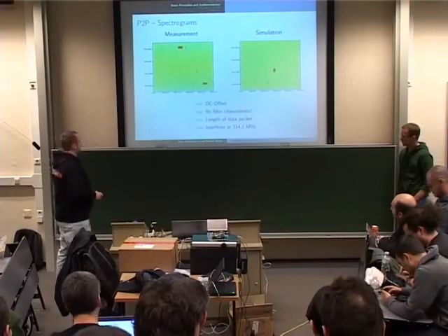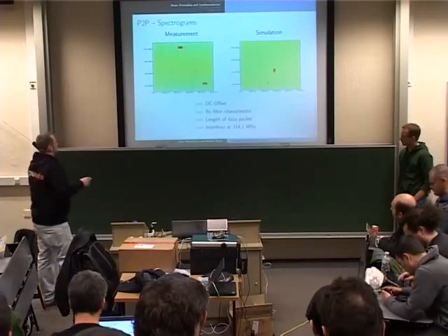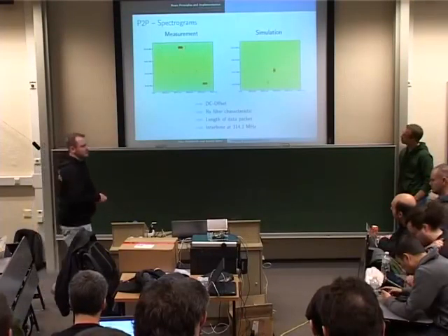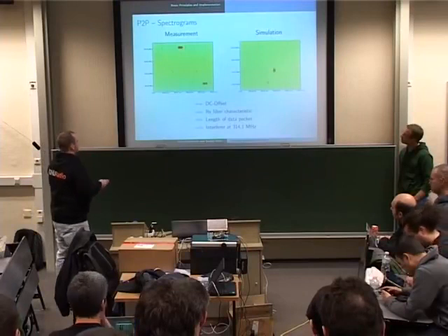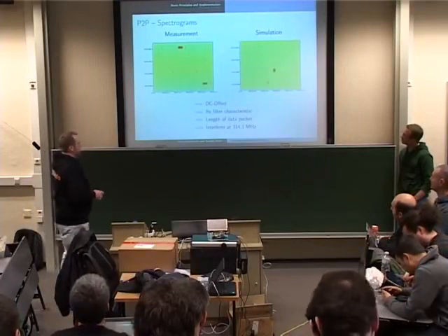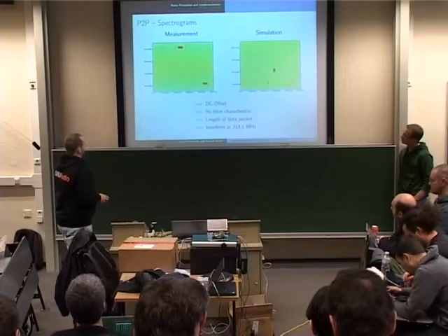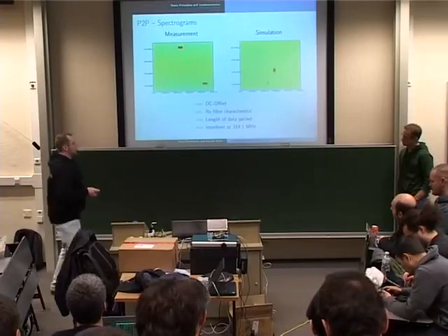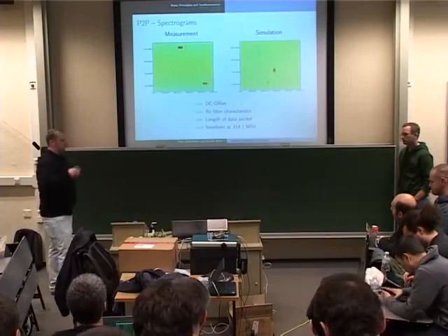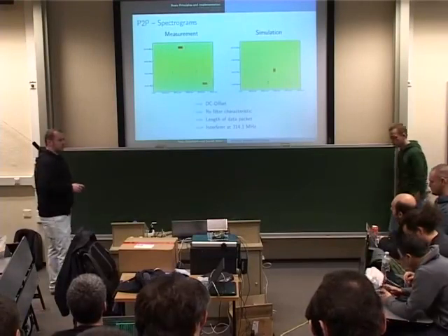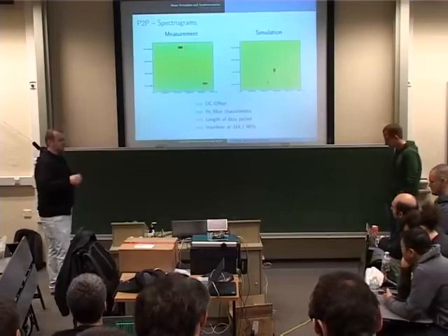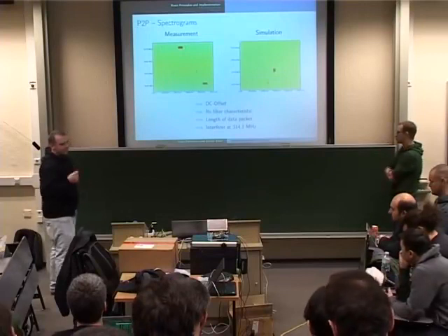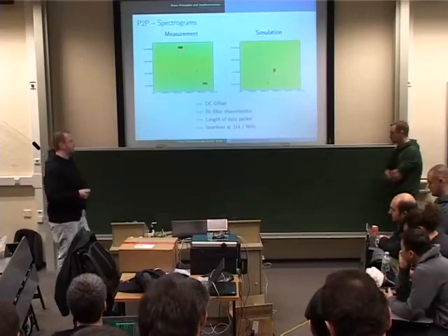As you can see here, the differences right now are that you don't see the DC offset, which would be very easy to implement, or the RX filter characteristic, which is implemented already, and yes, the data packet and the interferer at 340 MHz. That's also an opportunity to push interferers into the whole simulation, to test your network in the presence of an interferer, or perhaps in the presence of a secondary user or primary user, when you think about cognitive radios.